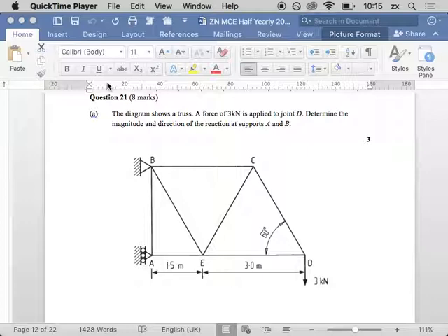There's only two other forces on this truss, right? We have our 3 kilonewton force. I'm writing minus 3 for 3 kilonewtons. How far away is it? Its perpendicular distance is 4.5 meters. Exactly right. I'm going to write it as 1.5 plus 3, and then I'll write 4.5 above that, just to help me understand where I'm going. Is that going clockwise or anti-clockwise? If I put a pin on B and twist it, yeah, clockwise, that's right. So I'm going to turn that minus sign to a plus.